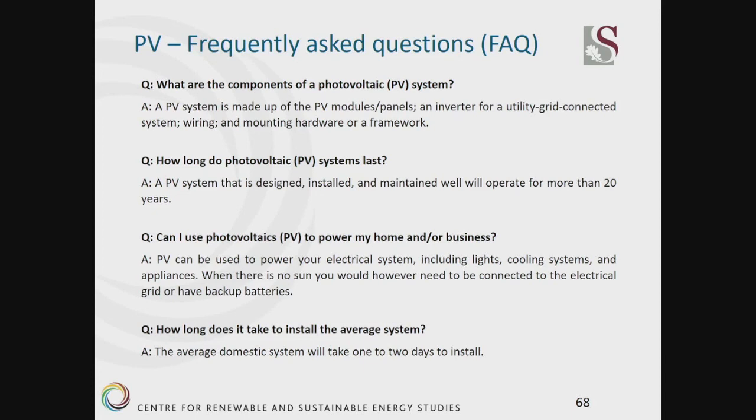Make sure that if somebody tells you that you will be safe from load shedding if you install a PV system, that PV system can actually provide power when not connected to a grid. Or you might need a special inverter that can do that, but it will use backup batteries. So just make a note of that.